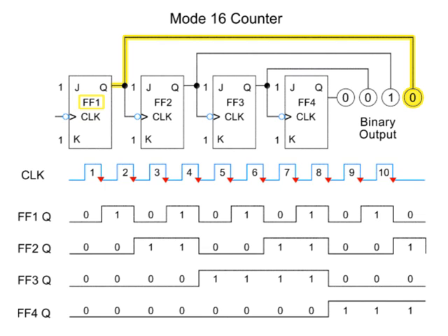The 1's position, or A, must change its state on every count. Thus, flip-flop 1 must toggle for each clock pulse. The 2's position will change its state half as often as the 1's position. Thus, flip-flop 2 will only toggle half as much as flip-flop 1. The 4's position will change less often than the 2's position, and the 8's position less often than the 4's. Thus, each more significant bit will toggle fewer times.